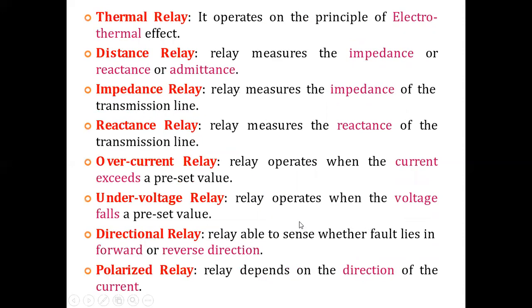Then thermal relay. It operates on the principle of electrothermal effect. Then distance relay. Distance relay measures the impedance or reactance or admittance. Then impedance relay. The relay measures the impedance of the transmission line. Reactance relay. Reactance relay measures the reactance of the transmission line.